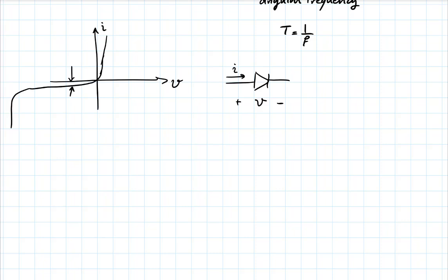And we simplified this in several steps, but we said, you could even go as simple as something like this to represent its behavior approximately. Something that, without any positive voltage, would allow essentially any positive current, and it would allow no negative current regardless of how high a negative voltage you apply to it. Okay? So this blue line, or these blue characteristics, are what we called the characteristics of an ideal diode.